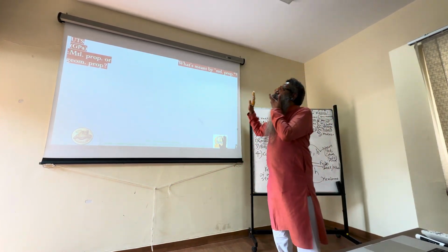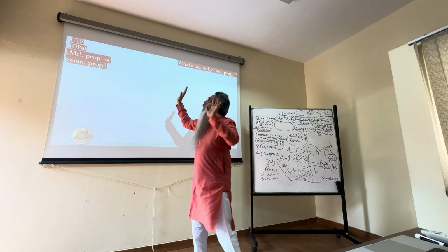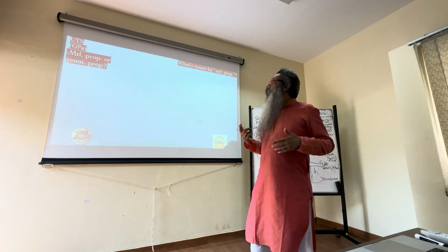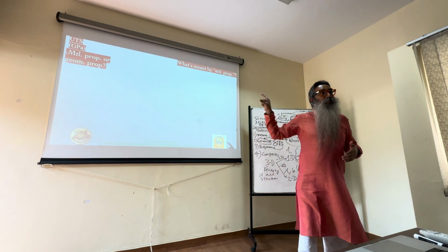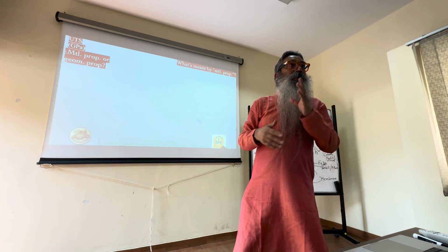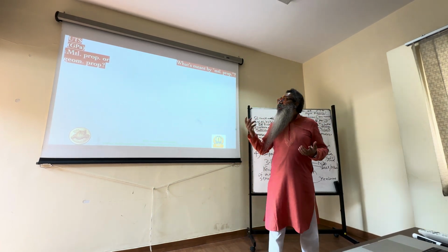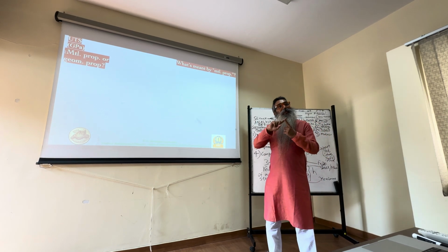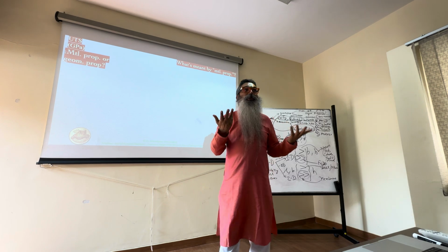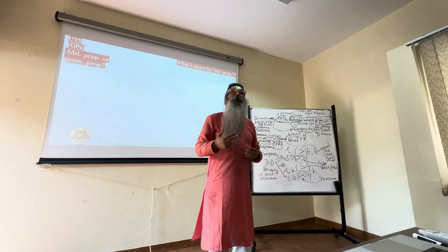Okay. So right now we are not even talking about fibers. We're generally asking, is the UTS itself a material property or a geometric property? But it's very good, Ivan, that you pointed out that whenever there is anisotropy, that is, a material is not isotropic, then to some extent there is geometry involved, because the direction in which you measure comes into the picture, and direction is always a geometric feature.